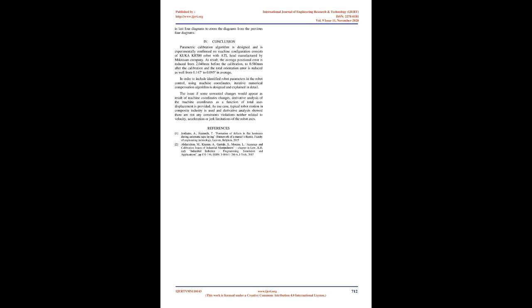In order to take full control of each robot axis motion, some algorithm of the look-ahead class of algorithms should be applied, so after the complete trajectory planning every machine coordinate would be expressed as a function of time t. Analysis of the performance of some of these algorithms can be found in 14. Application of such a trajectory planning algorithm to express the robot machine coordinates with respect to time t is out of the scope of this particular research.